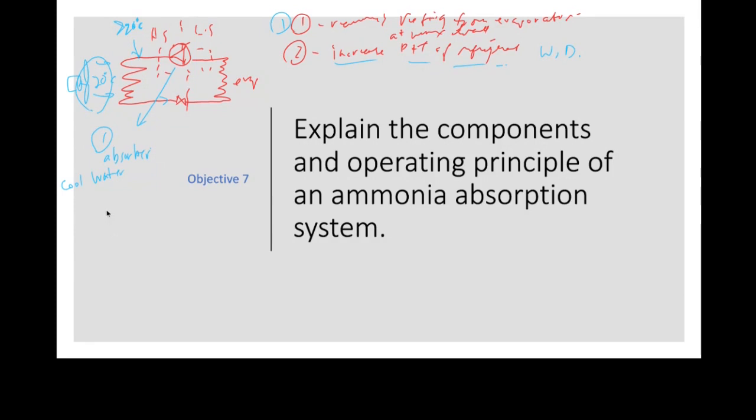Actually, at high temperature, it's like a deaerator in a steam plant. We heat up the water, and it gives off dissolved gases, right? Well, same thing here. We're going to heat up that water, and it will release the dissolved ammonia. But that's done by another component. So the first component is going to suck the refrigerant out.